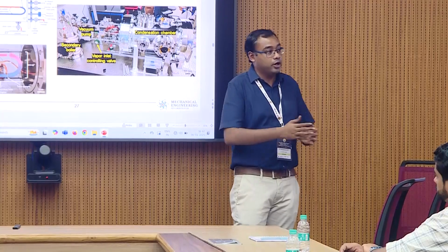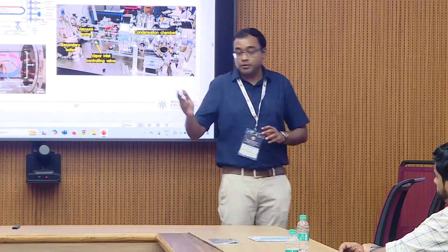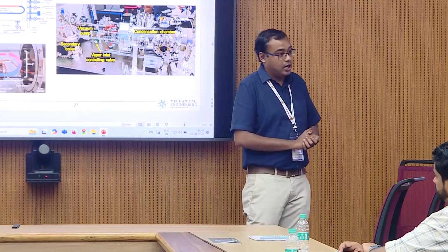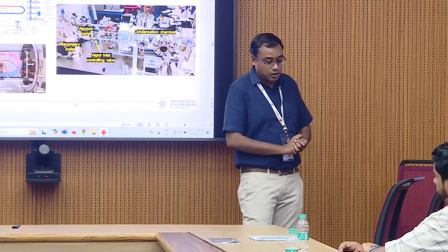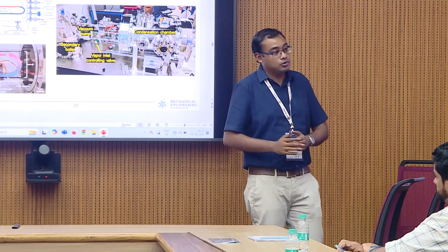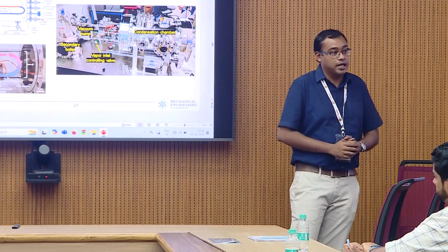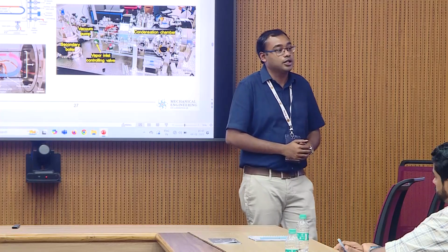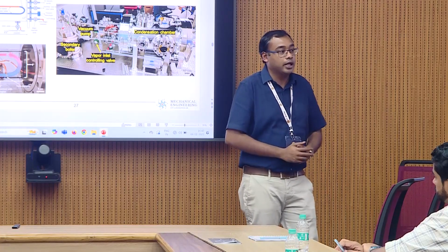the experiments that I showed over here are in pure vapor. In a pure vapor, for dew harvesting, of course there won't be dew, but in case of water harvesting, it is going to be a superhydrophobic surface. But in case of, let's say, atmospheric dew, you have the non-condensable gases, and I think Professor Arvind was also covering that earlier today. In the presence of non-condensable gases, the dynamics can be very different, and Professor Pallav works in the same direction, where what we find is it's not necessarily that a non-wettable or a superhydrophobic surface would be the best. It may so happen that film-wise condensation on a superhydrophilic surface is your better bet in dew harvesting.